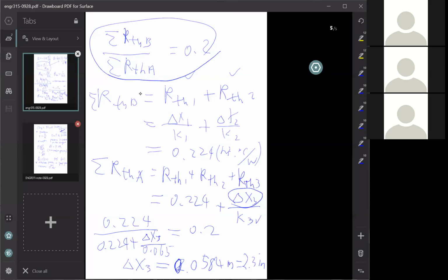I had a question for the quiz. In the big overall Q we had the delta X because of the thickness. When we're solving those individual parts with T1 and T2, is it okay to just say it's negligible, or would you have to actually include it? You don't have to, because I already said the overall Q is equal to the individual Q for each part. That's the total heat transfer rate, the same inside the entire system. So you would just use either the convection or conduction formula, not put it together, to solve for T1 and T2.